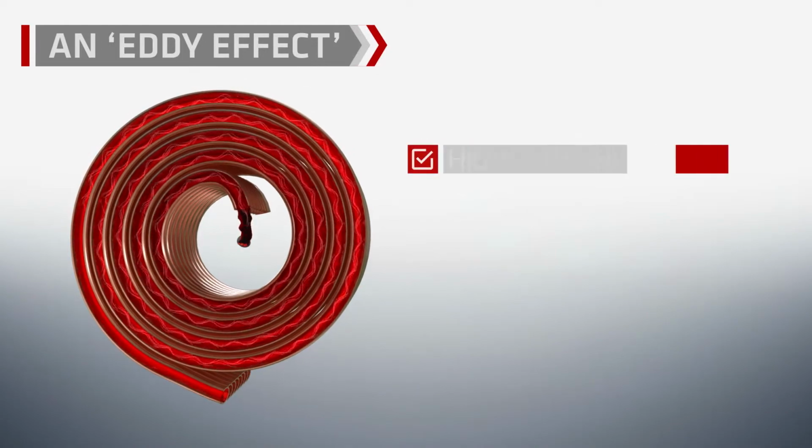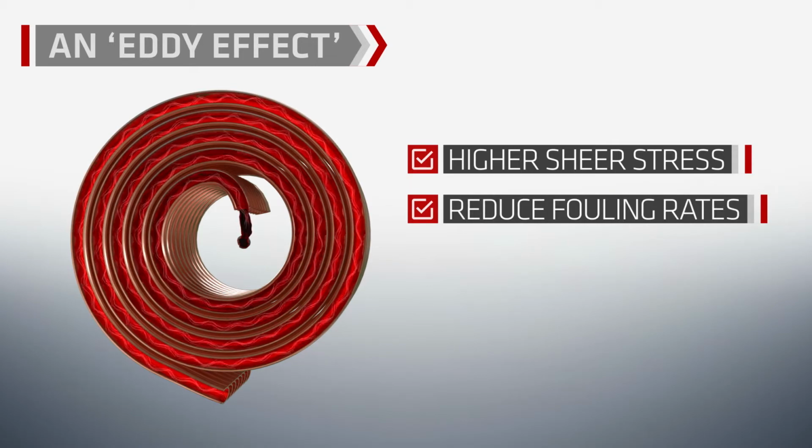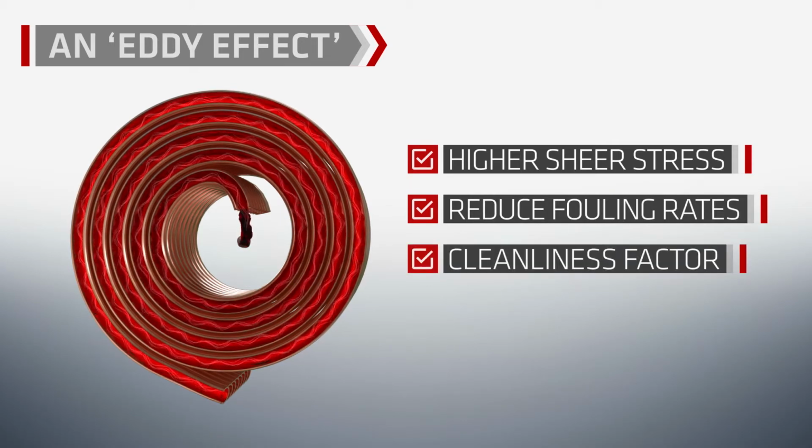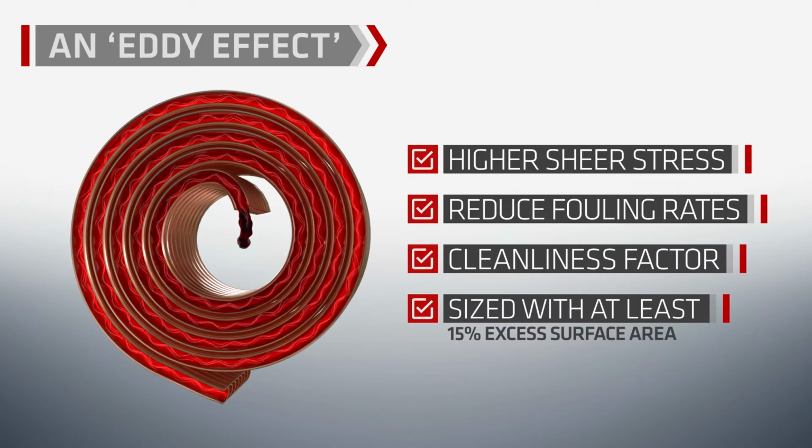Heliflow's eddy effect also creates a higher shear stress at the flow boundary. Both advantages greatly reduce fouling rates. Instead of sizing the Heliflow based on a fouling factor, we use a cleanliness factor. We typically size our Heliflow heat exchangers with at least 15% excess surface area.